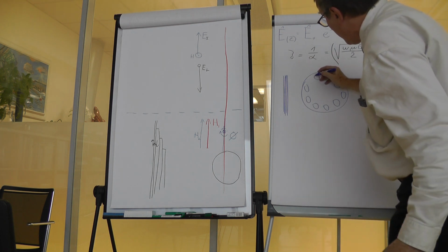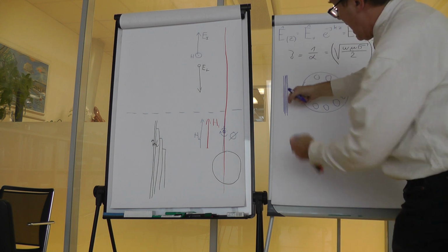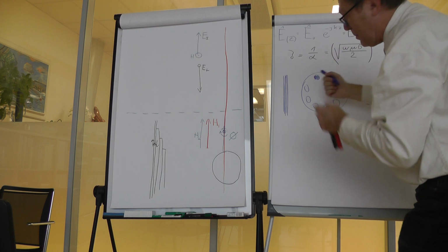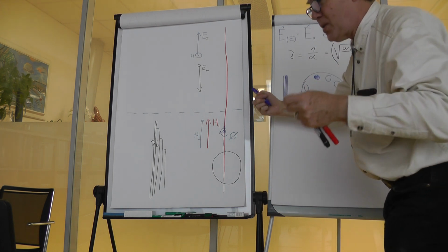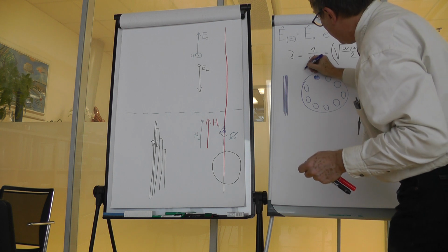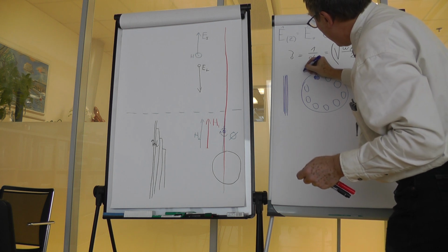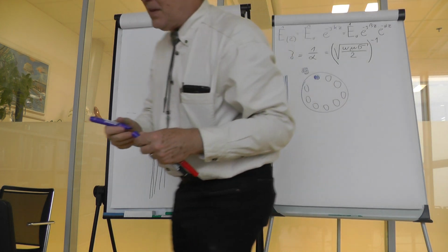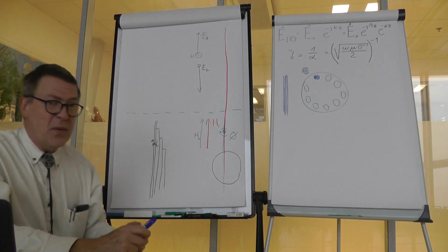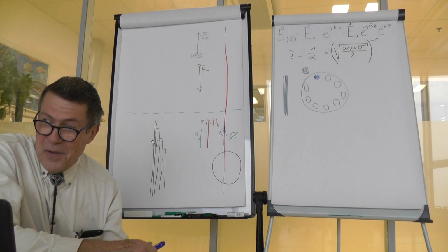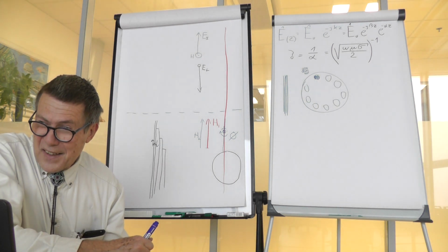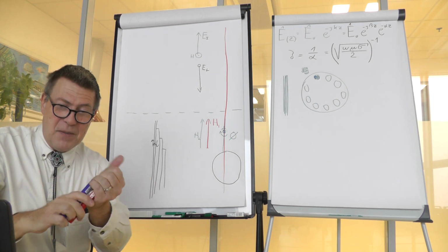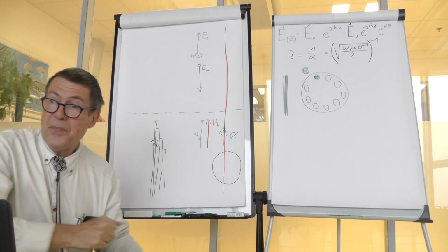And now the manufacturing process is that you have a number of needles that you put in, and then you connect them at both ends of the magnetic circuit, so that you have much more surface in this. Well, I am drawing circular conductors, but to have a maximum use of the space, this is done using rectangular conductors to save the free space which happens between circular ones.